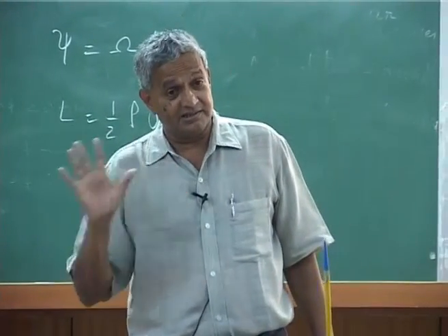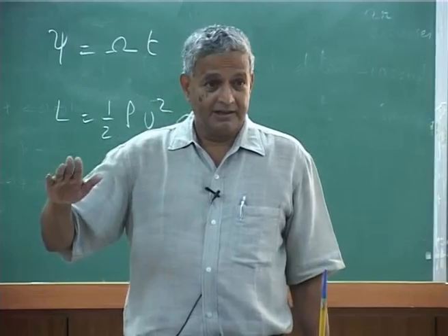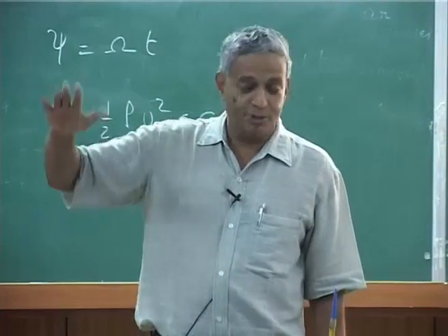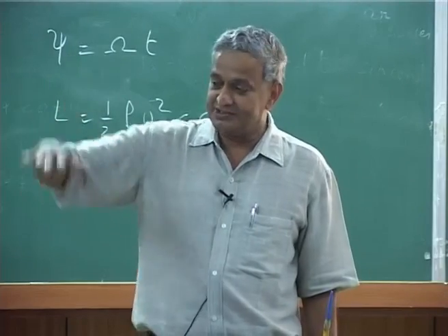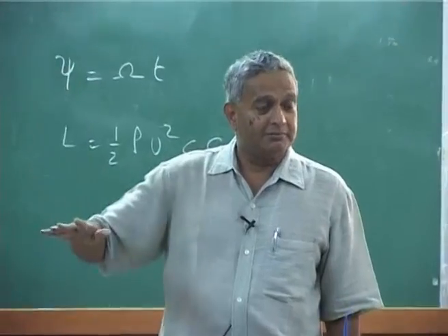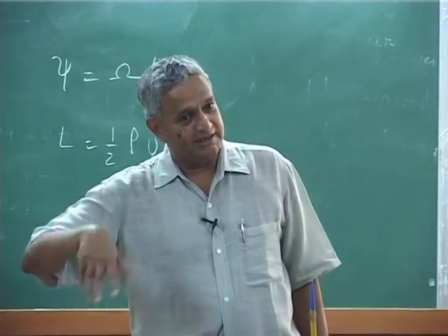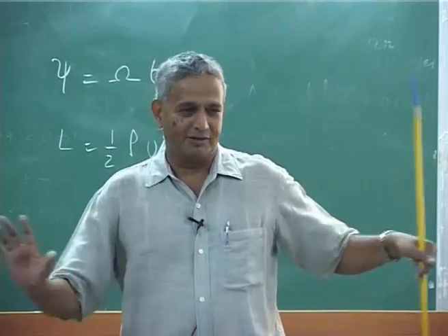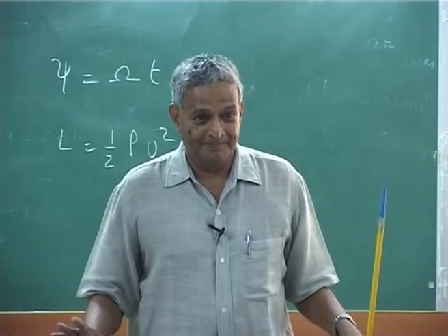This is a steady case. Now, here the V is changing, because of the V the load is changing, because of the load change this is going to oscillate up and down. When this oscillates up and down, that is going to change the angle of attack, everything. So this is the simple aeroelastic problem, but it is complicated.